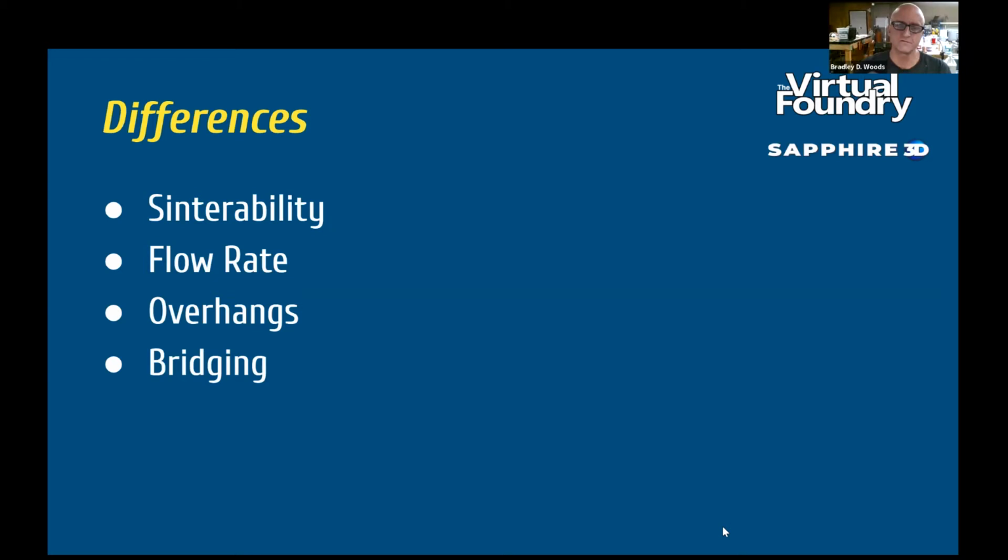Okay, it doesn't come up so much in bridging. Well, it could, but there's a side effect of the retraction that just keeps things moving more smoothly. If you add a bit of retraction at some point in each layer, like maybe at a layer change, just the act of moving the material in and out keeps it moving more freely.